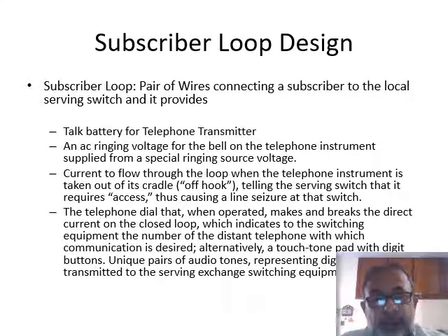It is installed, it is terminated into it. From the internal rosette, a line cord connects this internal rosette to the telephone set, with RJ11 connectors on both sides, and after that there is the telephone set.